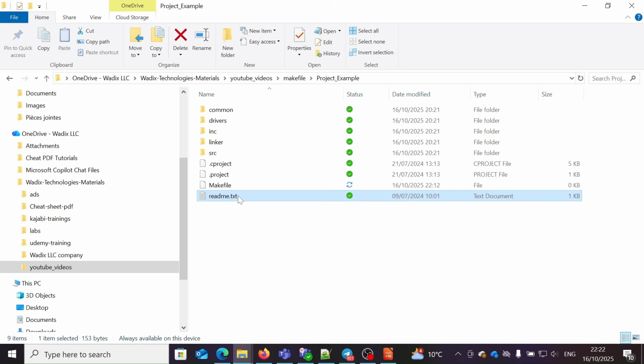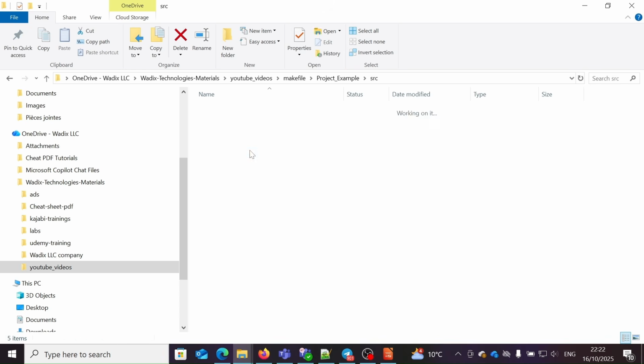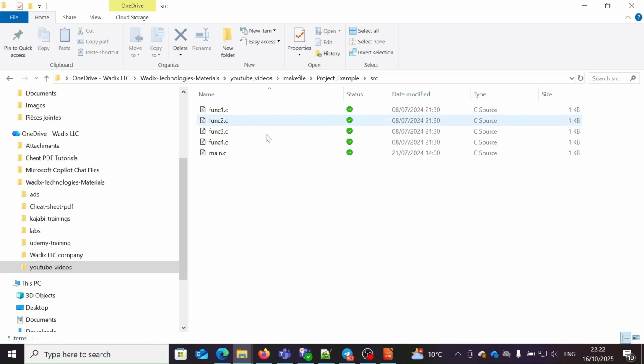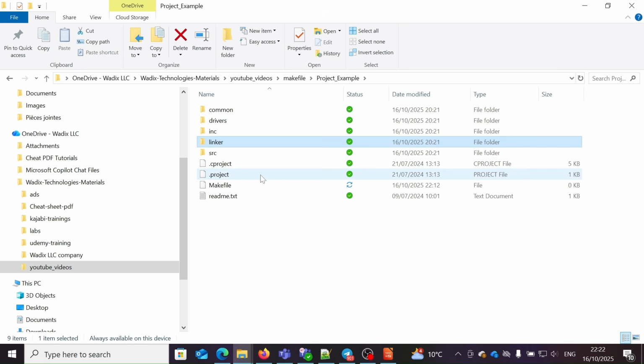Now, before jumping into your Makefile and start coding there, you will need first of all to take one step back and then try to break down the different inputs and expected outputs out of this Makefile. This is an embedded based project, so it consists of set of C sources as well as headers and linker file. Now those ones are needed by the compiler to be able to generate the object files, then link them to generate the final binary to be loaded into our hardware.